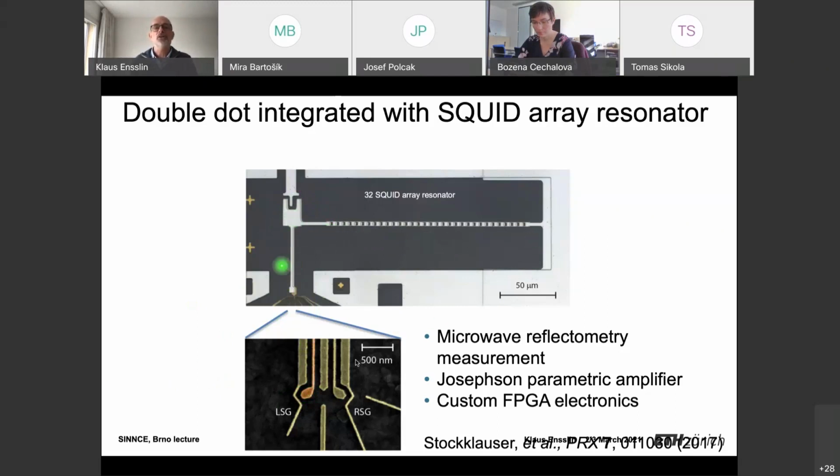So the voltage oscillates on this gate, and if this voltage modulates a charge, then this gives rise to an additional capacitive signal, and that means that the resonance frequency of this resonator will be changed. So the resonance frequency will depend on whether there is an electron or whether there is no electron. And not only the resonance frequency, but also the Q and so forth.